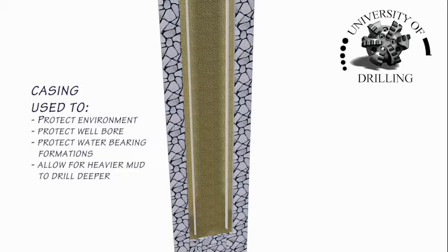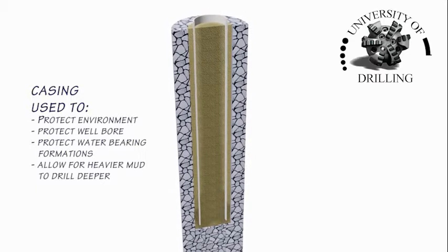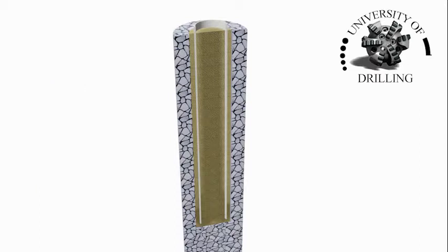keeps pressure on the rock to prevent fluid ingress into the borehole, while the casing is being run into the hole. Tubular steel joints, or casing, are assembled and run into the hole, where they will be cemented in place to protect weaker rock formations from the heavier mud needed to drill deeper rock formations, and to prevent water or explosive hydrocarbons from coming to the surface to pollute the environment, and to protect other permeable formations like groundwater formations used for drilling water.